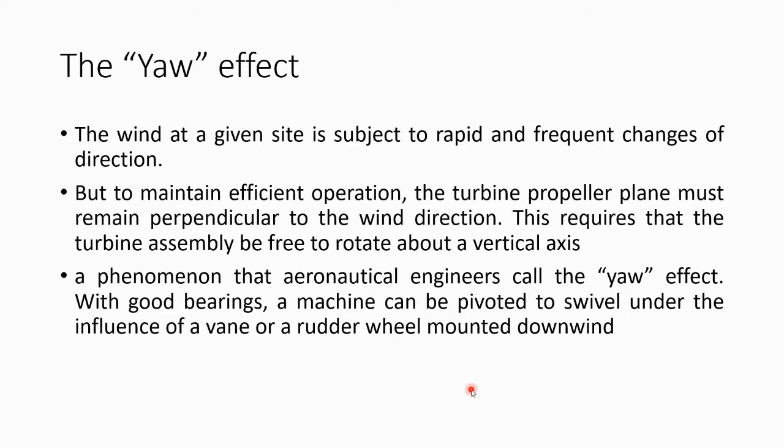And to achieve this, it requires that the turbine assembly be free to rotate about the vertical axis, meaning that you want the rotor to always turn. Okay, you want it to turn and always face the wind. So this is a phenomenon that engineers call the yaw effect. Okay, when you try to make this turn, with good bearings, a machine can provide a swivel under the influence of a vane or a rather wheel mounted downwind. So a yaw